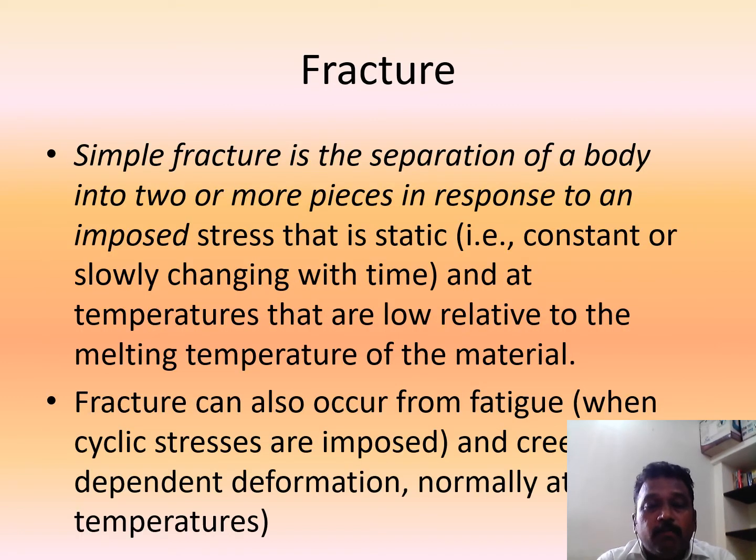And then comes the fracture. So what is a fracture? A simple fracture is a separation of a body into two or more pieces in response to an imposed stress that is static in nature, that is a constant one or slowly changing with time, and at temperatures that are low relative to the melting temperature of the material. This is very, very important. We are not conducting the test at the melting point of the material, so there is no point in conducting a test at melting temperature. The temperature where the experiment is carried out should be very low relative to the melting temperature of the material.